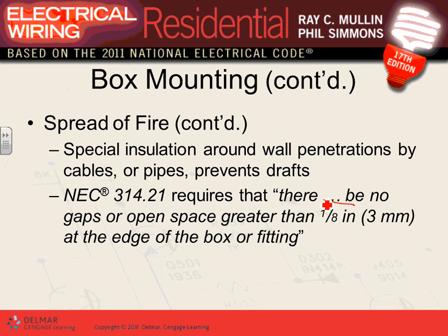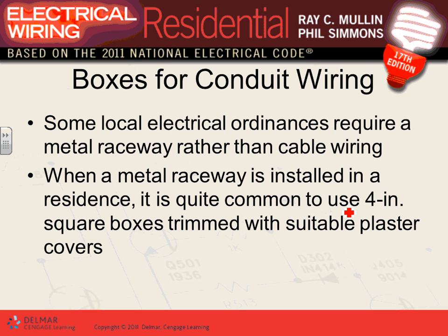No gap. We talked about the no gap, 1/8 of an inch. If you have a gap, when you put your box, if your box, guys, is more than 1/8 of an inch away from the wall, you are supposed to go fix it. It's all about the speed of fire.